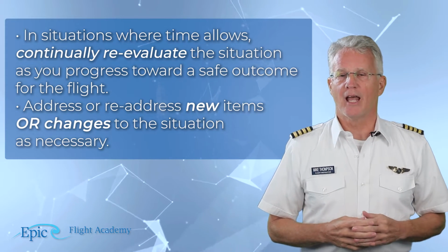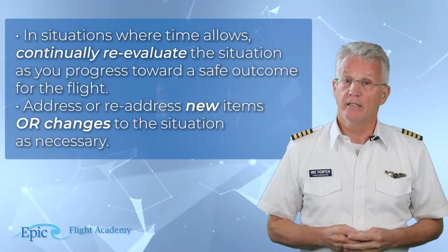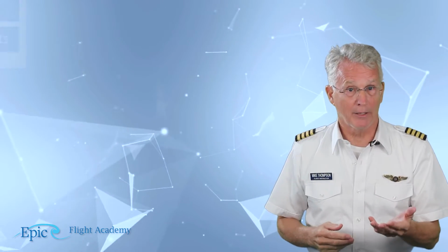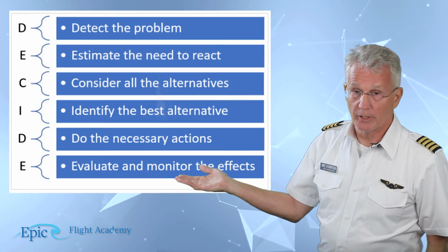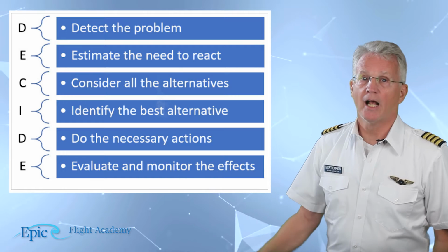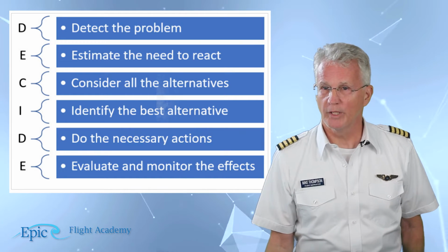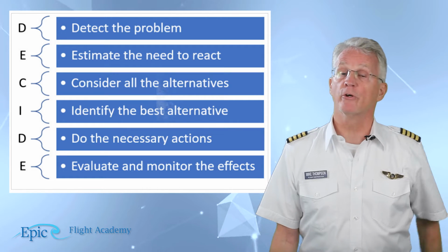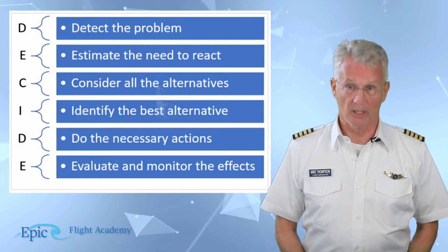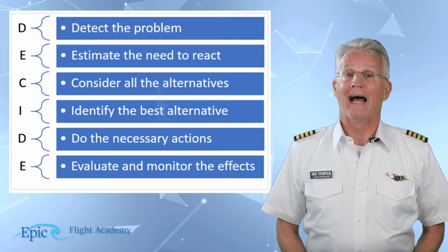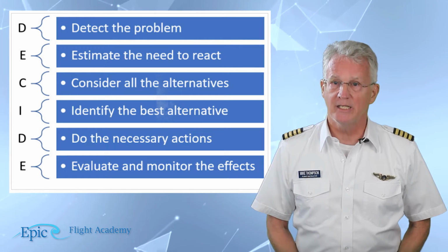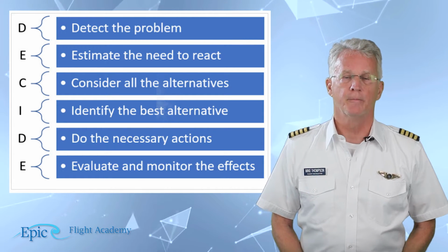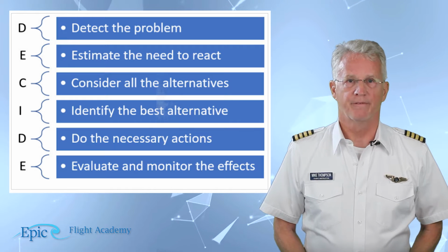This is the last E in the DECIDE model, and you can see that model here. Continually evaluate the situation and circle back to the first D for detect and move through the model again and again as needed to guide the flight to a safe outcome.